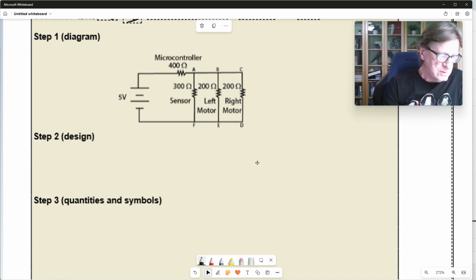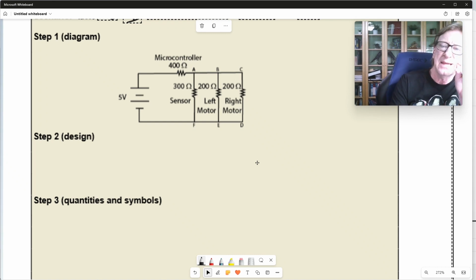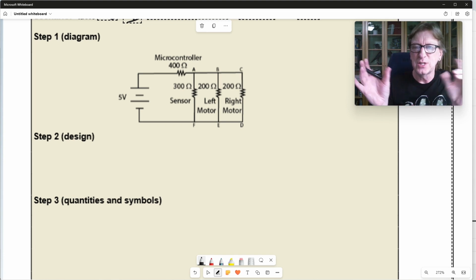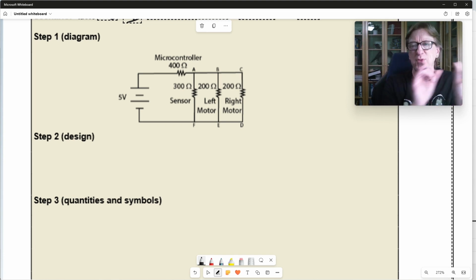All right. So what we're going to do, we need our minimum loops. Now, a good rule of thumb is anytime you add a loop, you need to put a new component in there. What happens a lot of times is you'll think you've got a different equation, and it turns out that it's just a modified form of an equation you already have. And so it doesn't help you. You're still short one. Well, okay, that's not tragic. You just go back and find another loop and put it in there.